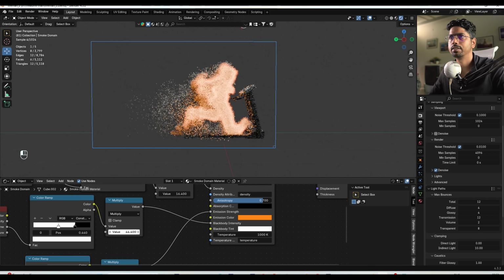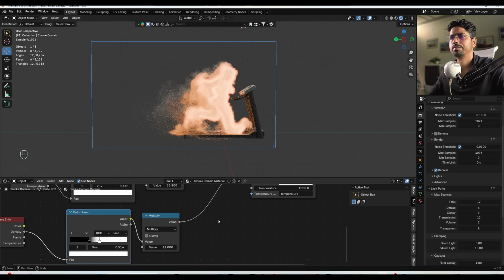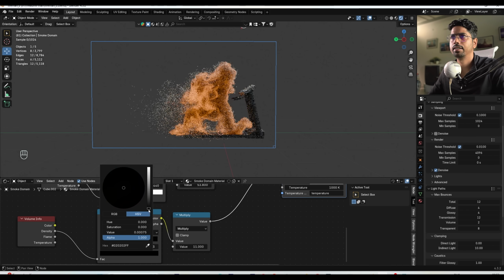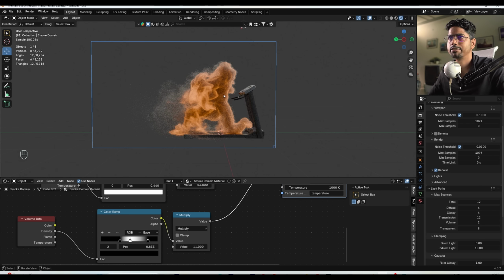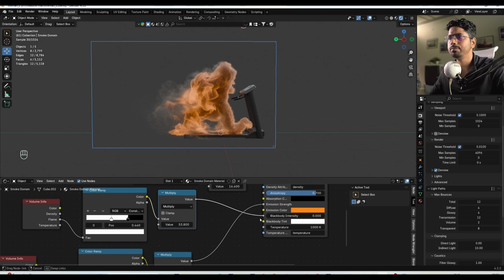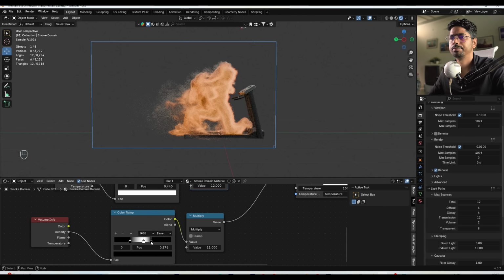Here I am going to increase the black body intensity strength. Let me hide the black body intensity, and let me Control click here, and let's add the black. So basically I am shrinking these factors, so I can only focus on these flames. So you can see, this way I can really target that flame without affecting these black body. So let me make it 12, let me 25, 12 actually.